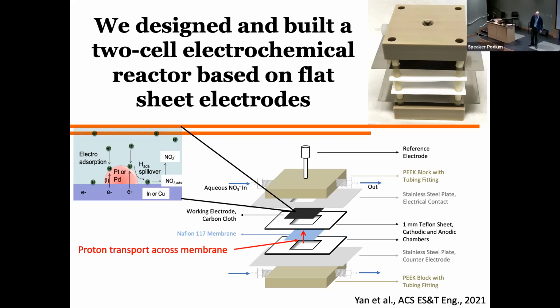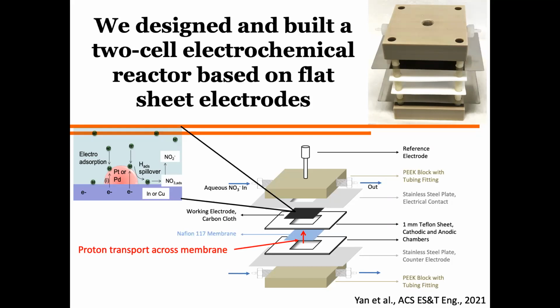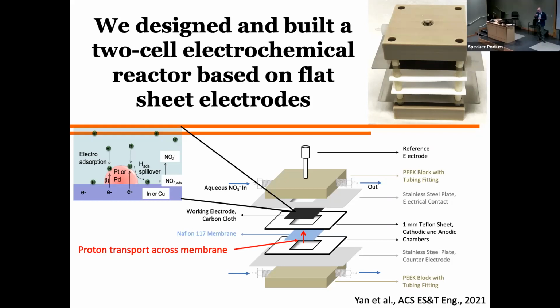Okay. So first, the trickle bed reactor. When we fit for the different flow rates, both the liquid and gas, and got the intrinsic mass transfer rate, we did look at counterflow operation, assuming that the mass transfer rate constant would be the same. The difference then would be the concentrations of the hydrogen relative to the nitrate. And in that case, just from the simulations, we don't really get much better performance in that system. And so it's really limited to around the reactivity that I was showing.